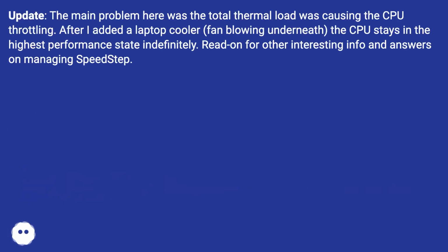Update: the main problem here was the total thermal load was causing the CPU throttling. After I added a laptop cooler, fan blowing underneath, the CPU stays in the highest performance state indefinitely. Read on for other interesting info and answers on managing SpeedStep.